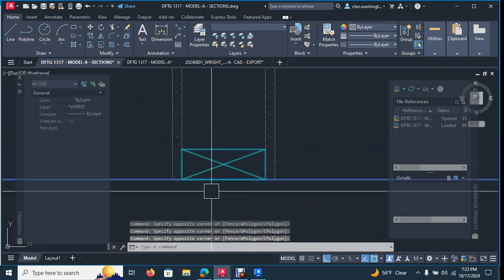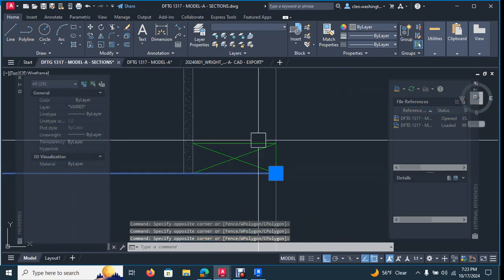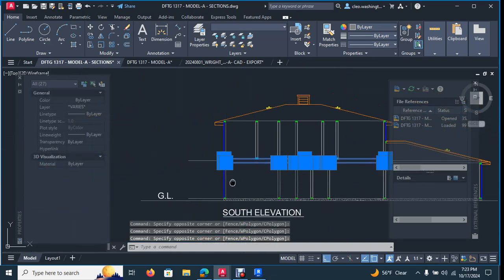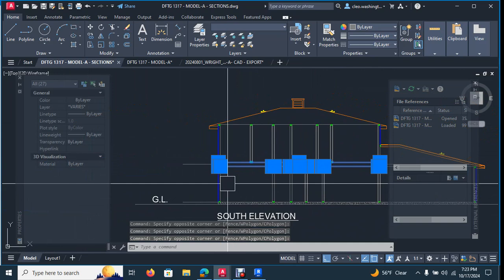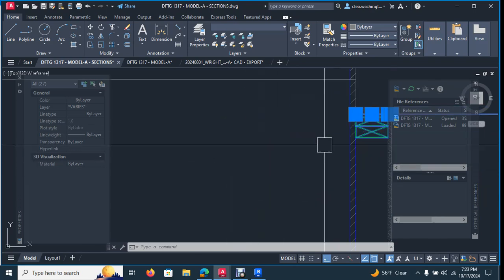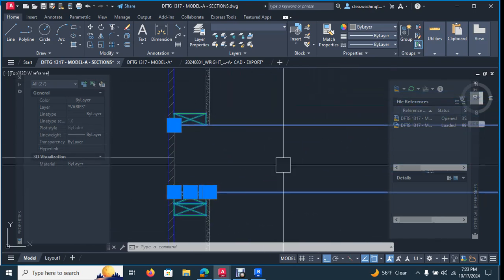And actually, when you get good enough, typically when I do these types of residences, if I'm using AutoCAD, then I'm sketching a section out on sketch paper. And I'm drawing the section first. Reason being, the section will drive how your elevation and your floor plan is going to look. But that's when you get some experience and you actually know what you're doing.